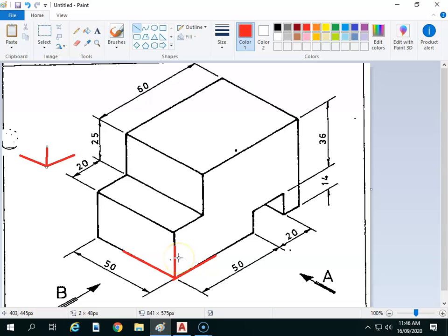Now, the important detail is that in isometric views, I'll draw a new line. This is, let me get a pen. This is 30 degrees, and this is 30 degrees. Yeah? And isometric means equal measure. The reason for that is that the angles are equal on both sides.